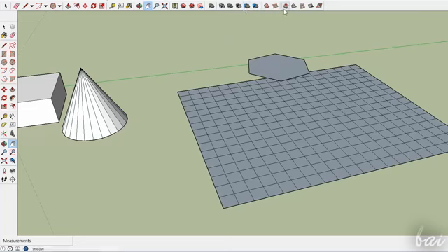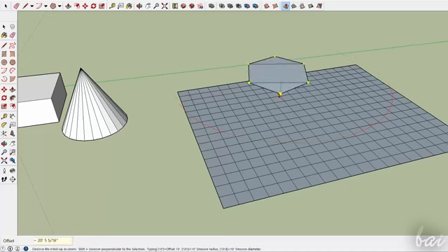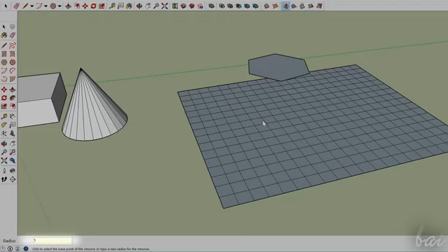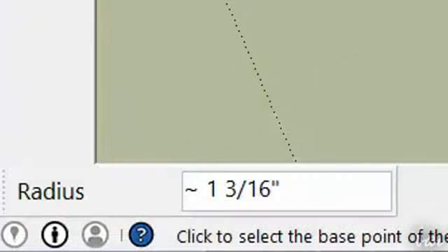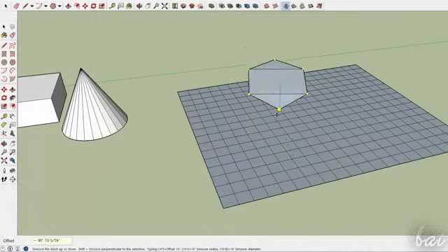The Smooth tool moves up or down a vertex, a side, or an entire face of a normal object, depending on your settings. First of all, define the active radius. Type in the number and use Enter to apply. The number will appear next to radius below. Then simply drag from one of the yellow vertices or any side or face you see.